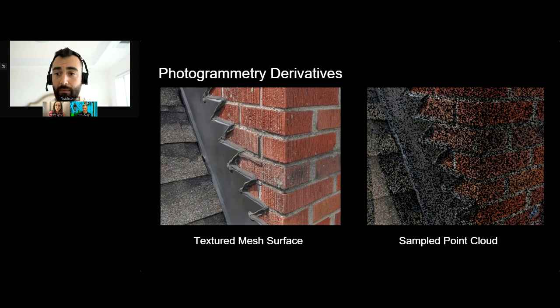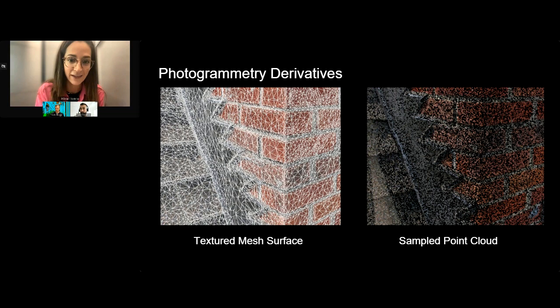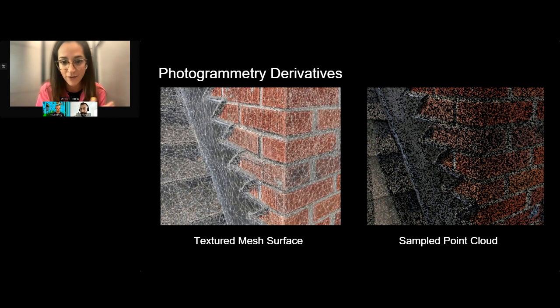And from similar there, to with the laser scan, Ted, I guess that planning your flights is essential, right? Like weather conditions, overlap, these kinds of elements that are going to have an impact on the quality of your final deliverables.